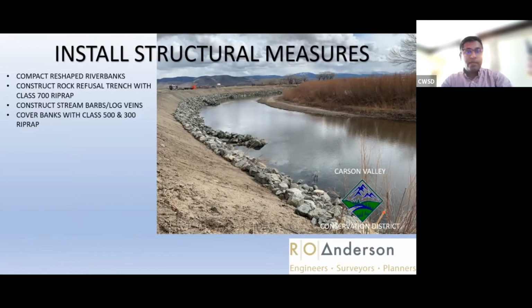Yeah, this is the slide that I was talking about. You'll see, I don't know if you can see, the road right on the bank, the newly installed bank. That is where the new road went, and the utilities, underground electric and fiber optic cables. We didn't want to take those away or move those. So we had to just adjust our slopes to 2-to-1, even 1.5-to-1.